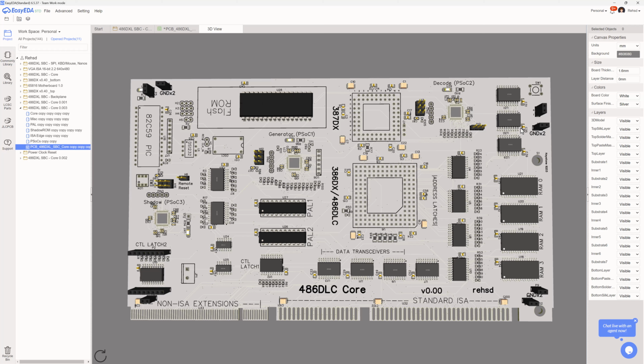So I'll be able to pull these 3 chips and this shadow PSOC off. And then also the flash ROM I won't need on this card, so I can pull the flash ROM off. And my intention would be to place really this PSOC for the shadow, plus the ROM itself that gets shadowed into RAM, plus these latches and any other supporting pieces that go with the shadowing process onto a separate card.